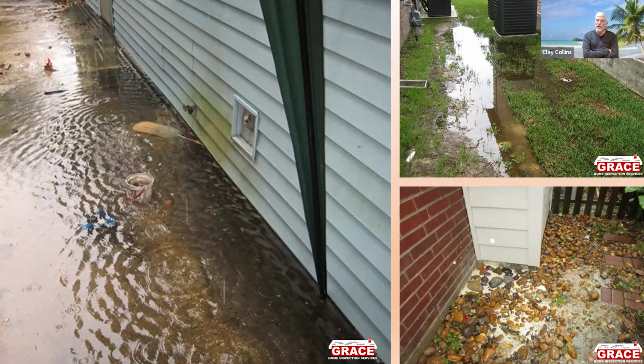But it's not running off. If you have water standing in that low spot, what's stopping it? Well, in that particular case, I believe it was a fence. It was not that picture below, but that picture below shows you exactly the same thing. They had some mud there. Well, the mud had to go away, so they put brick walkway up to the fence. That's not a gate, it was a fence. You have all the rock, you have the sand. They haven't fixed their drainage. All they did was make it a little easier to step on.